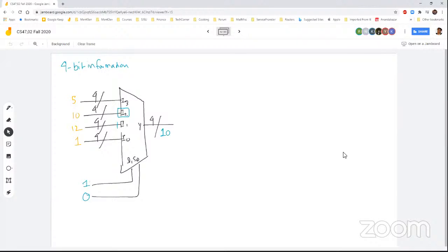So if someone missed it, what I was telling is that it depends on the selection of this multi-bit multiplexer, where its input is not one single bit, it is multiple bits. In that case, we are practically selecting a value. Though internally it is evaluating the logic, at the macro level we are selecting between values, and that's what gives the programmable capability inside the hardware through the multiplexer.